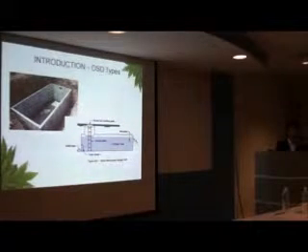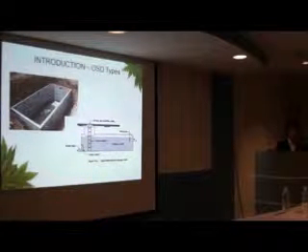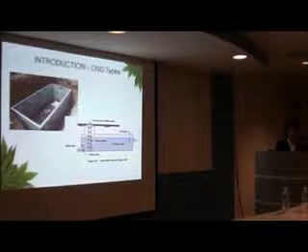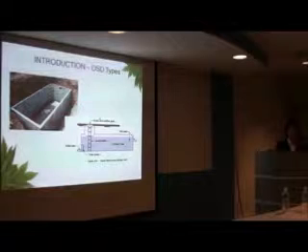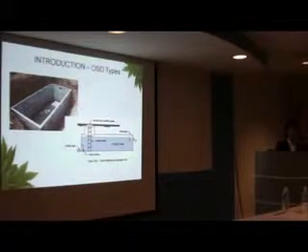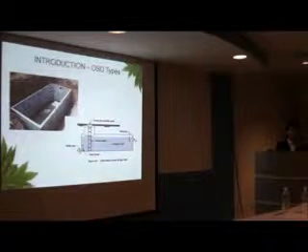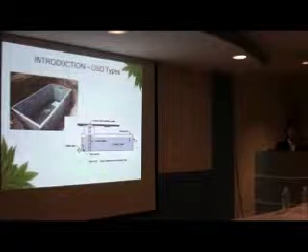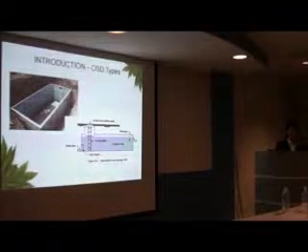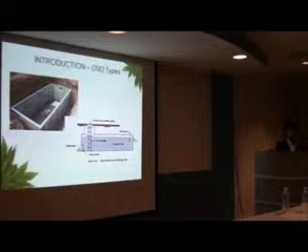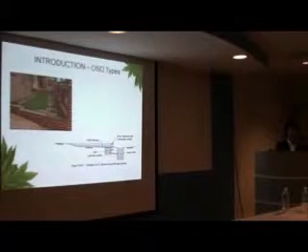The water will flow through the inlet pipes and then fill up the storage tank. If the water overflows, it will flow out from this overflow weir. And this is an outlet pipe, and there's a trash screen to screen out the trash so that the trash will not block the outlet here. This is a service ladder. This one is a typical below ground OSD. We look at another type, above ground OSD.